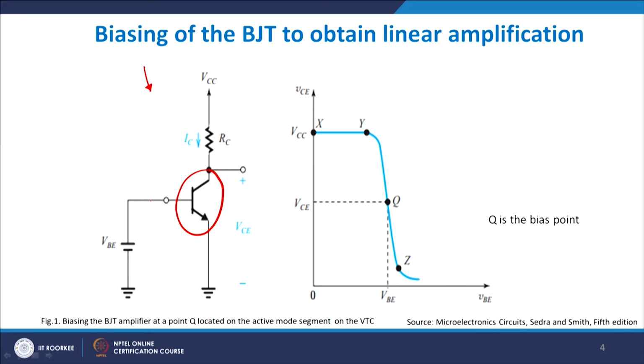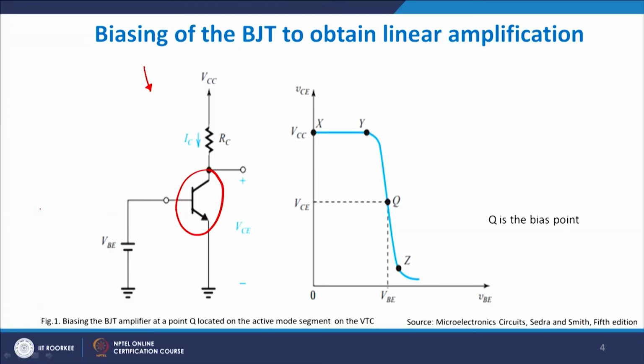Now, the obvious question: how do you physically amplify? When you amplify any signal, how do you do that physically? First of all, you apply a DC bias onto the device itself, which you are supposed to amplify. Once the DC bias is applied, you need to superimpose the small signal model over the DC bias in order to sustain an output voltage variation. So I mark my DC level, and superimposed on that I have an AC cycle, which multiplied by the voltage gain AV gives me the output for any BJT. That will come later on. Let us see what the functionalities of linear amplification are.